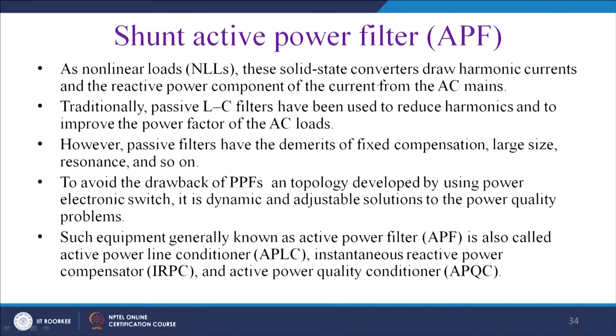Akagi et al. in 1984 proposed basically the shunt active power filter. As a nonlinear load, this solid state converter draws harmonic current and the reactive power components of the current from the AC mains. Traditionally, passive LC filters have been used to reduce the harmonics and to improve the power factor of the AC loads. However, passive filters have the demerits of fixed compensation, large size, and they can actually have a resonance with the power supply and so on.